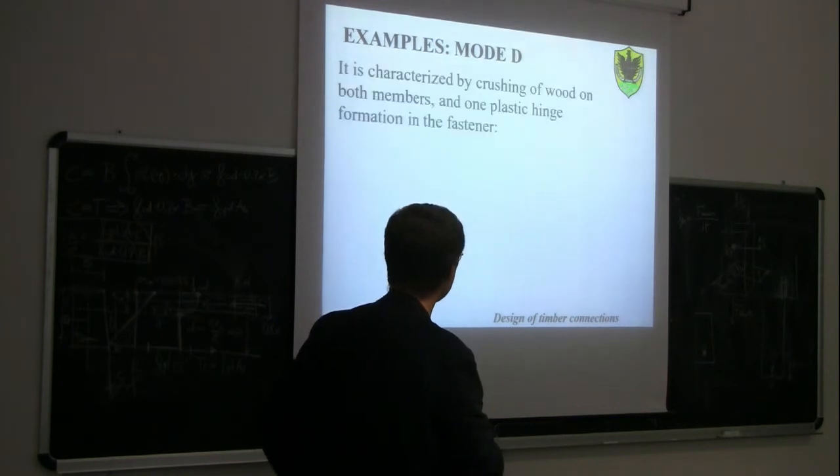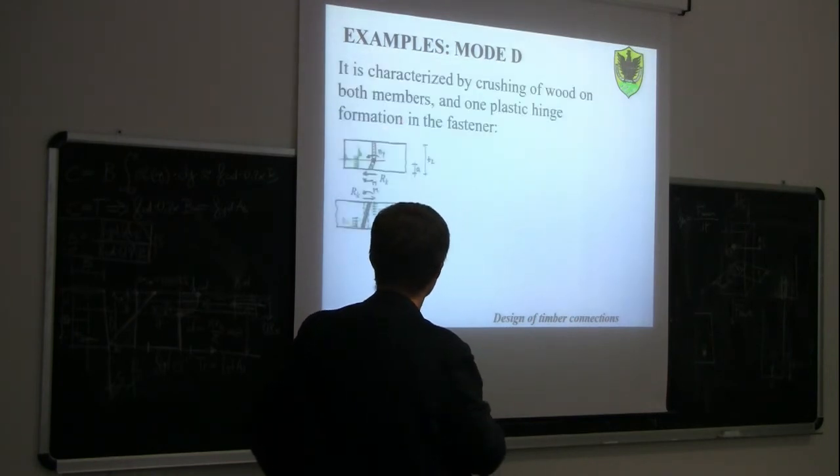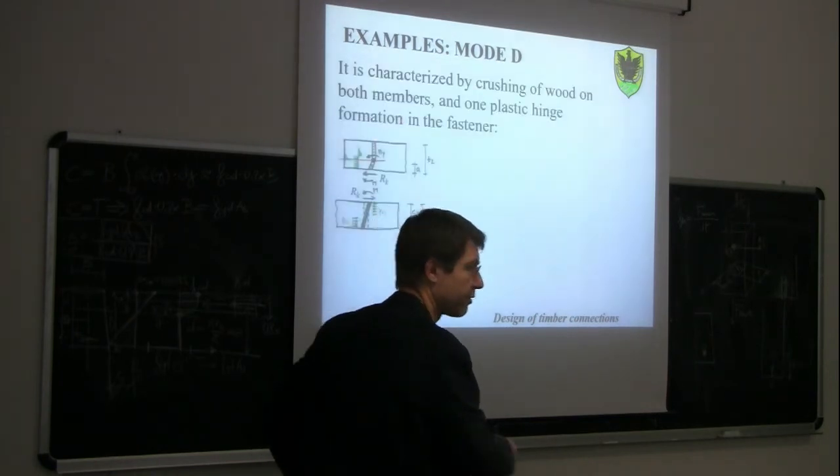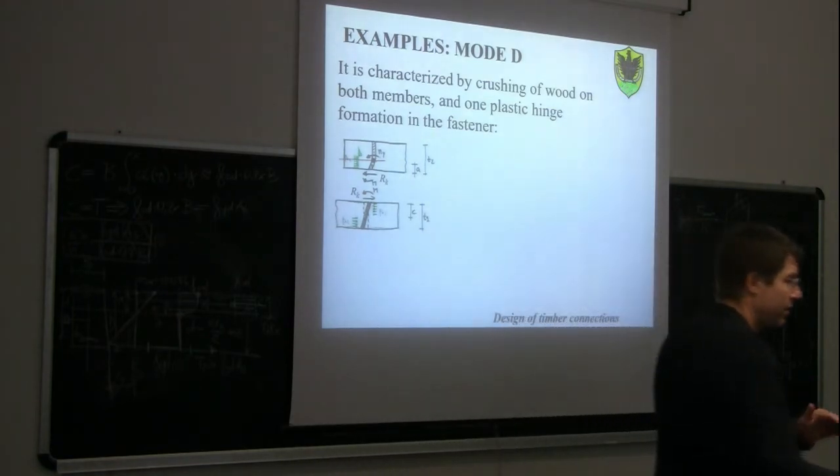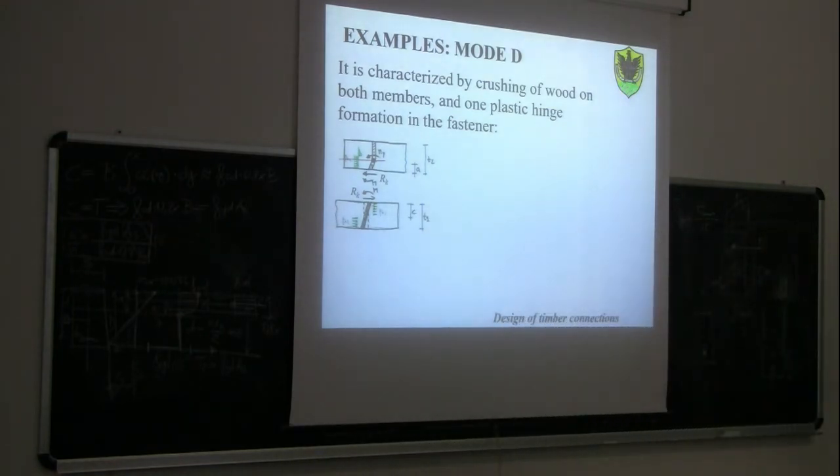So we have first to separate the 2 members across the shear plane. t2, thickness of member number 2, t1, thickness of member number 1. Once we separate the 2 members, we have to write down the unknowns. So Rk will be the shear force transmitted here on the shear plane.